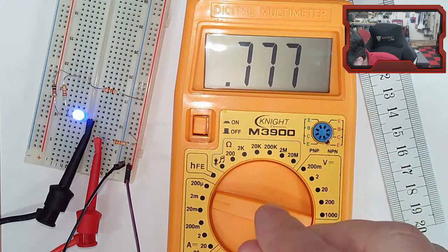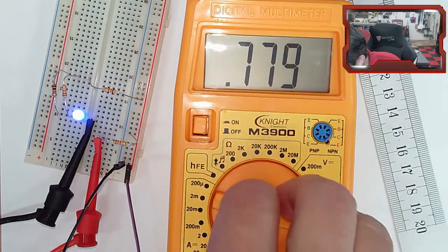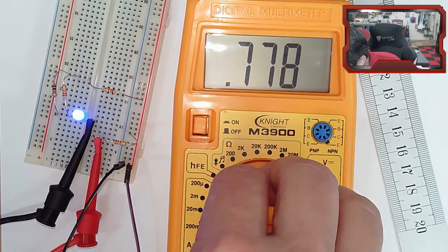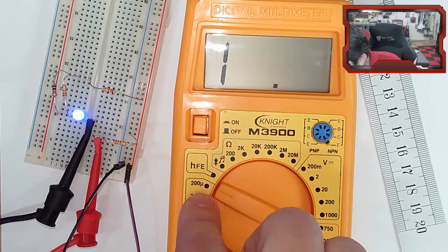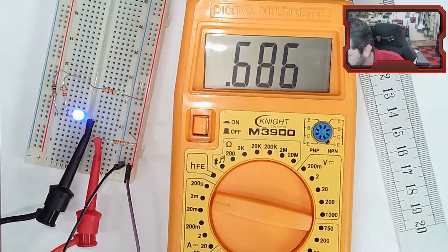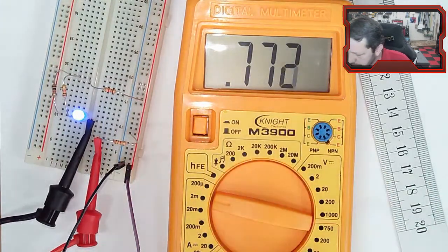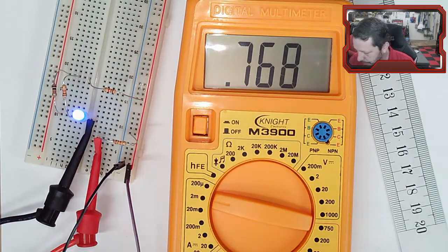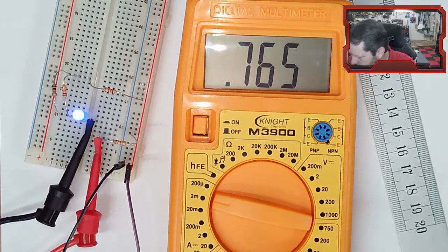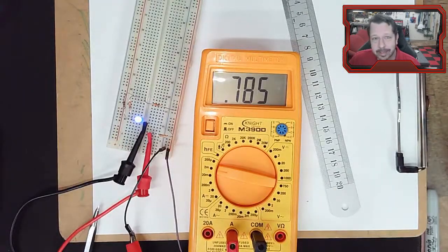Depending on the range, you get slightly different readings. But if we go to the microamps, we're above 200 microamps, so it's not going to read that one. 0.77 milliamps, somewhere there. So a very low current, but we can measure it. And so I just wanted to make sure that we knew how to do that. I'm probably not going to ask you to measure current very often, but you may need to.